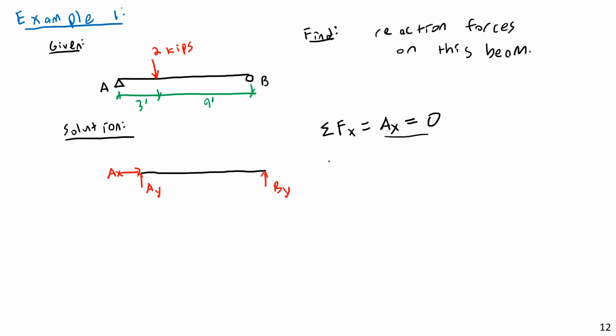Now, I could do a summation of forces in the Y direction, but the problem is I would have AY and BY as unknowns there, so I'm going to avoid doing that right away. I'm going to do instead a summation of moments about point A, and the moments I will have, well, first of all,